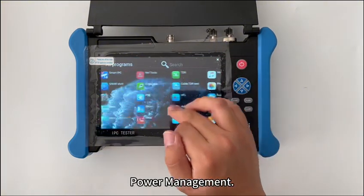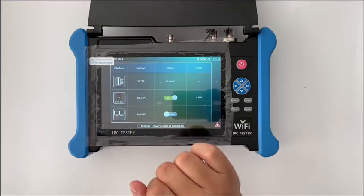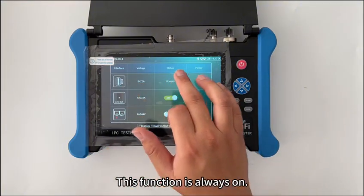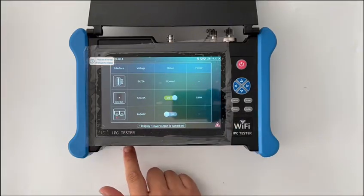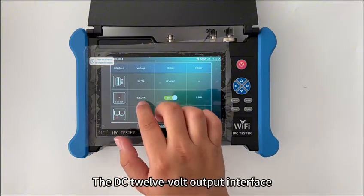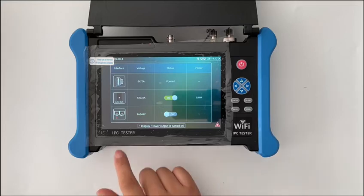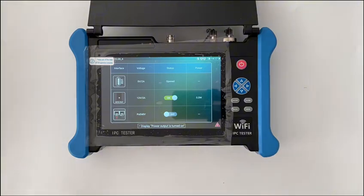Power management. Now let's explain the power management function. The power management function can set different power supply forms, including a 5V 2A USB power supply. This function is always on. We just need to connect the USB interface that needs power. Connect it to the 5V 2A DC USB interface to output the DC 12V output interface. It can output 12 volts and 3 amps. It can be used through the output interface below. 48V POE power supply can be output through the device's network port.